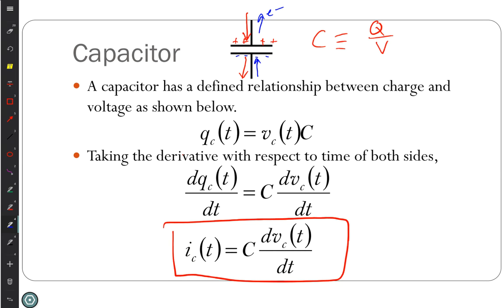So I have a current that flows to the capacitor on one side and from the capacitor on the other side. It just doesn't pass between the plates. Instead, it's charging the plates. So when I said the current through the capacitor, that was incorrect. It's the current coming to it on one side and leaving it on the other, but it was charging the two sides rather than going through. So it's an important thing for understanding what's going on inside a capacitor, that clarification of the words.